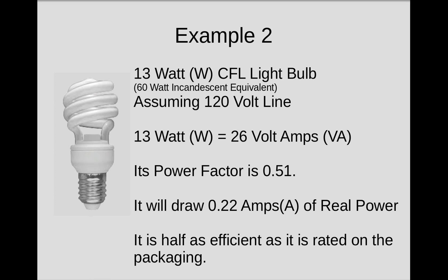So why is that important? The biggest reason why some people have maybe run into issues with this, and the reason why a few people were asking me about these bulbs, is people are taking lights that may be rated for 40 watts, and logically they're saying, well, my light fixture is rated for 40 watts. I'd like my light fixture to be a little brighter than it ever was before. I'm using these super efficient looking bulbs that are only drawing 13 or 20 or 26, 28 watts. In their brain, a lot of people are saying it's drawing less power.